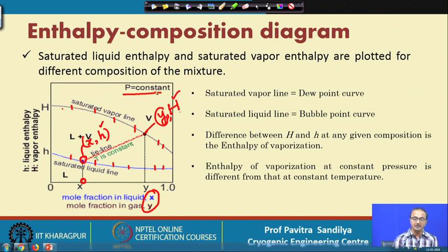Now, like earlier, if we join all the saturated vapor phase enthalpies, we get another curve. This is the dew point curve.